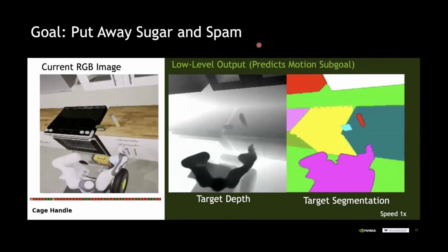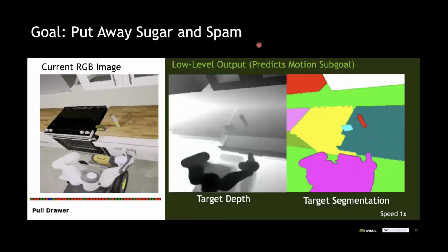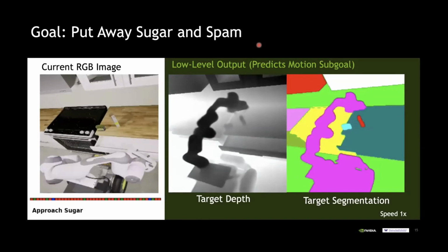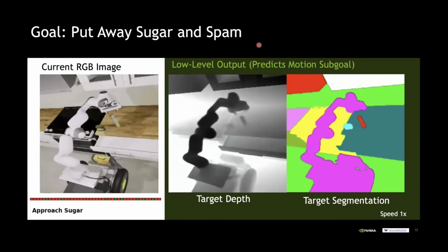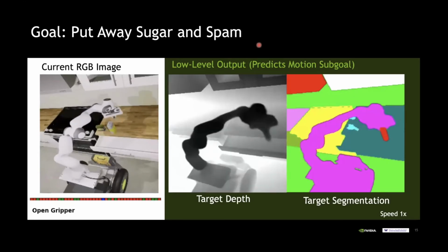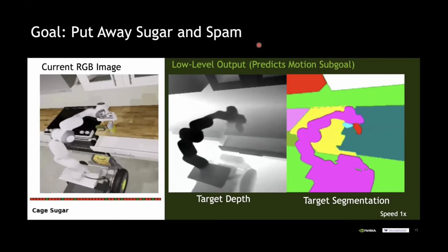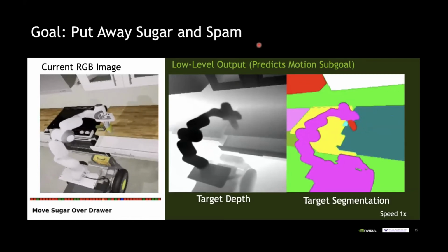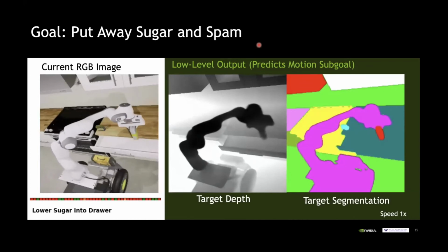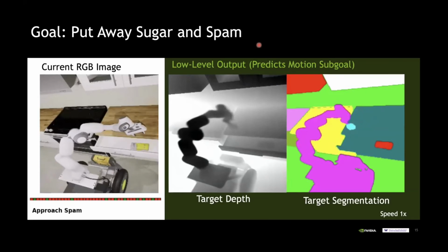Now it jumps to the handle. Once it has the handle, it jumps back, and the robot smoothly then follows those goal points in order to reach them, okay? So again, what the deep networks are doing here, on the one hand, they keep track of the logical state of the system. Then the planner generates, based on the logical state, intermediate high-level actions, and the deep network then translates these high-level actions into 60 target points for the gripper that the robot can then execute.